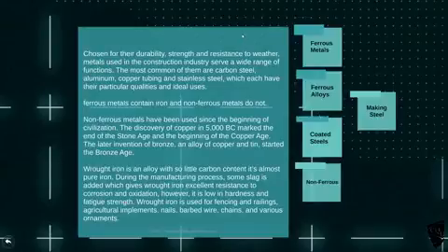Basically, metals, you pick them just because they're strong and they're resistant to the weather. Forget the fact that they're going to rust and corrode. If you look after them properly and select the right type of metal, then you won't have that problem. Most common of these metals is steel, or more precisely a carbon steel, and then you follow it along with aluminium, copper tubing, lots of your plumbing is made out of copper. Stainless steel's becoming quite popular.